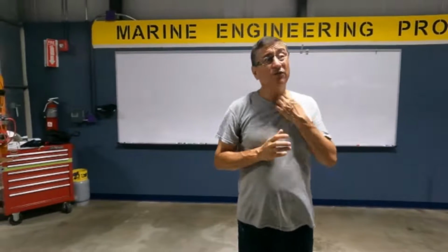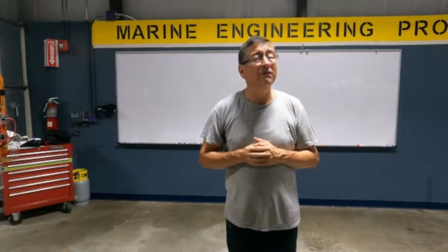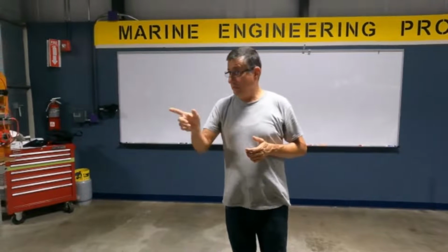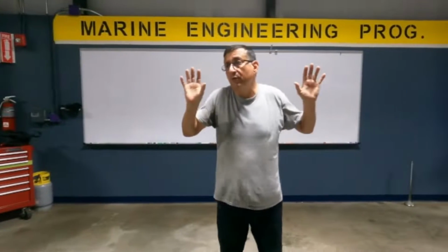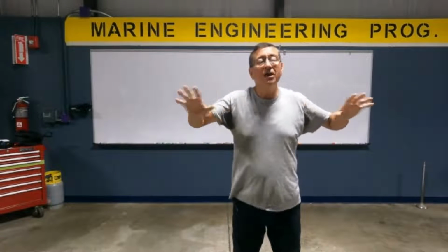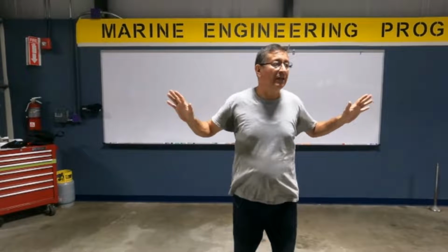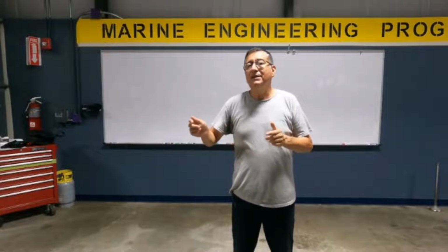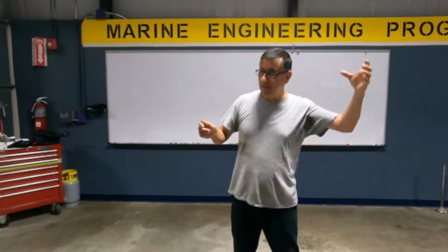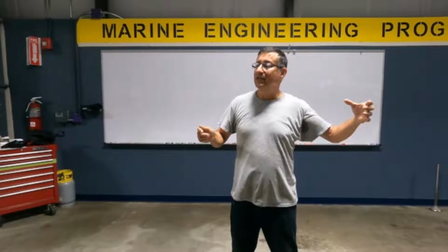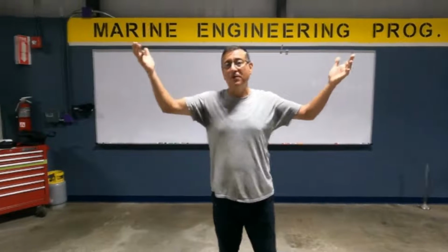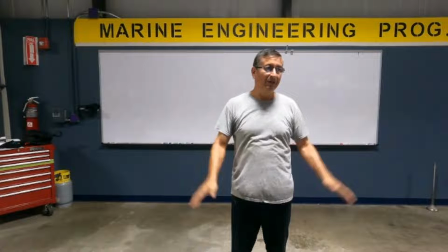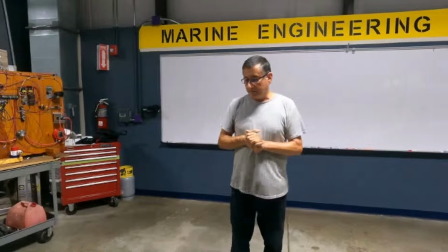No? We are going to find a lot of circuits in series. For example, the fire suppression system. If the fire suppression system is activated in the engine room for some reason, it immediately shuts down engines, generators, everything, to protect, no? Because the cable to activate the extinguisher bottle is in series with the main power of the boat. If the extinguisher is activated, the main power turns off. Good. Okay, series.